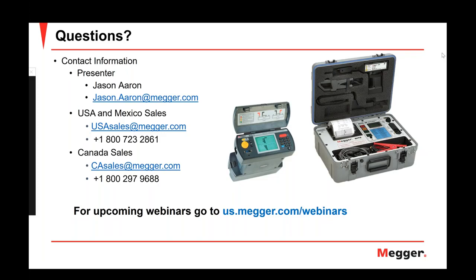So if you're talking about vented batteries that you have access to the electrolyte, the best way to get the temperature of the cell, or of the different cells if you are averaging the value, which is the recommendation, is to measure the temperature directly on the electrolyte. Any digital hydrometer that does that will give you that information. That will be the best thing to do.